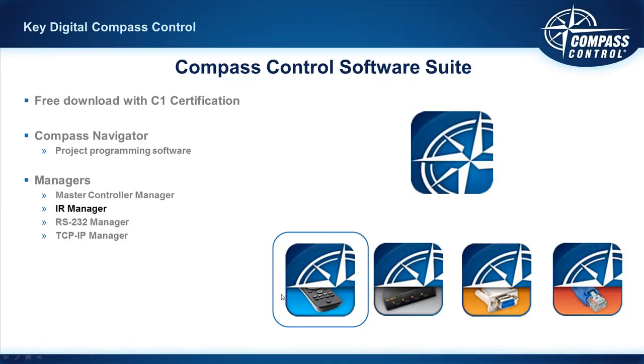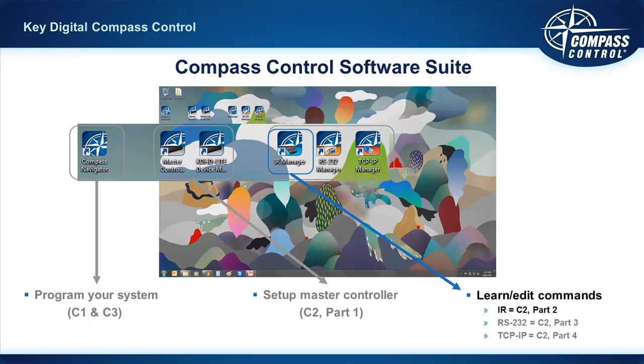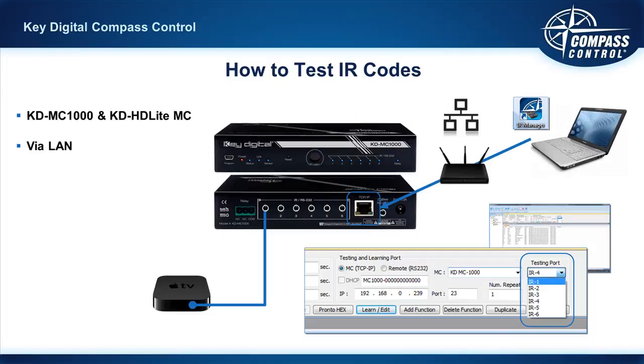The software that we'll be using to view, learn, and edit IR commands is the IR Manager. With the Compass Control software suite installed on your PC, you'll find the IR Manager with its blue nautical icon. And here we are going to teach you how we learn and edit those commands, and also how to test those commands.